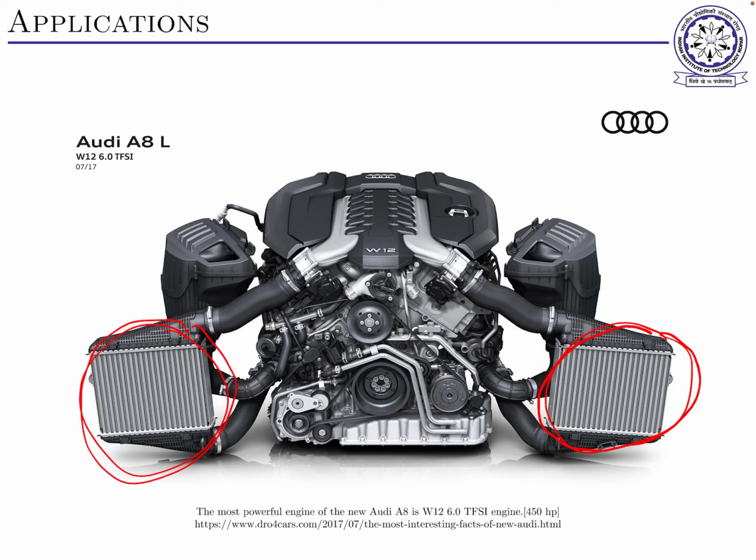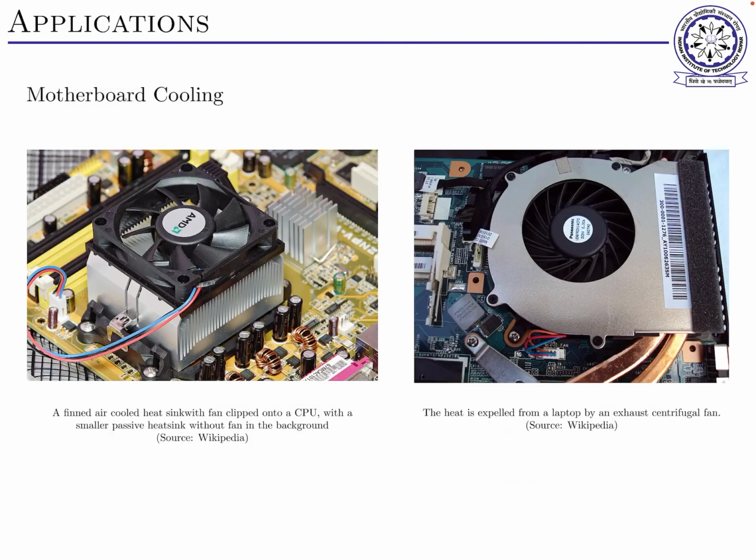Another place is where the crankcase is inside, so there is an enclosure outside there, where coolant is present. Coolant is a liquid that takes heat away from the surroundings of the combustion chamber. So in that way multiple fluids are used. Here air is used as a medium, and inside there is water coolant. Forced convection takes place because there is a pump there. One of these pulleys drives a pump, and that pump pushes this fluid all around. So that is one application.